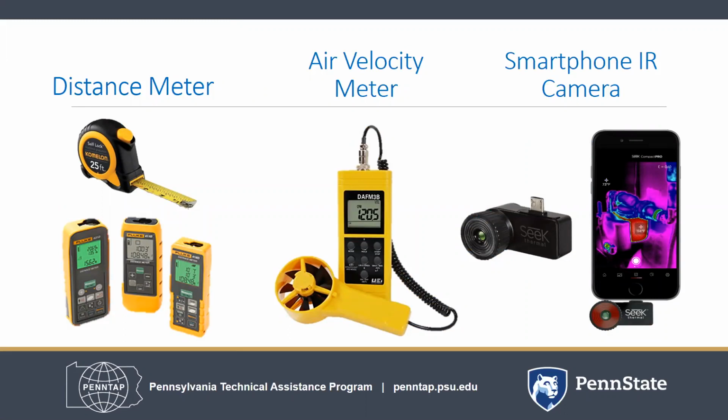Other helpful tools include laser measurement tools, which can assist in the square foot calculations. Very handy for when you might not have a second pair of hands to help you. Air velocity meters measure airflow. This can help you understand what your baseline expectations are, but also show you, per se, a clean air filter versus a dirty air filter. These tools are all low cost and immediately helpful.